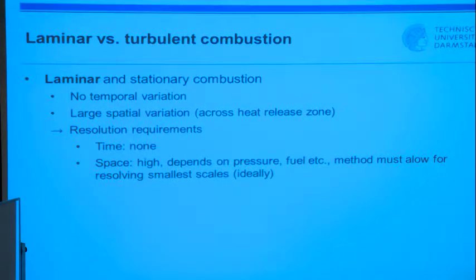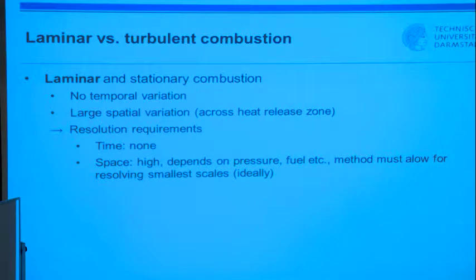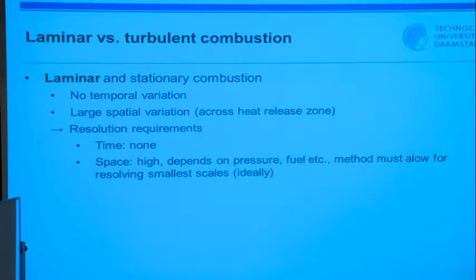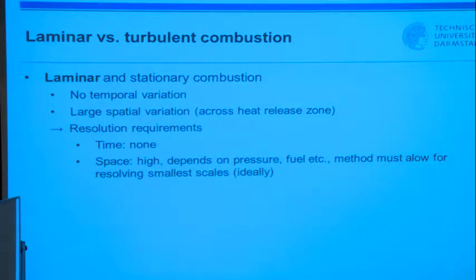By experience, making a laminar flame stationary is really difficult. You have to protect it from any movement in the lab, and so even there, very often, although you have a laminar flame, it might change its position. It flips back and forth, such that in reality you still need a sensor which has a certain time resolution, smaller or better than the fluctuation of your flame.